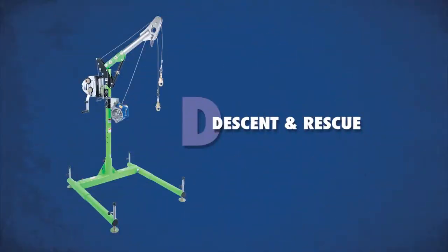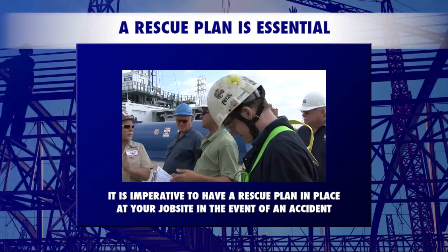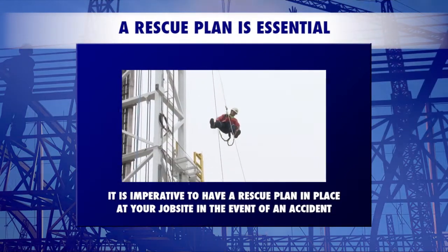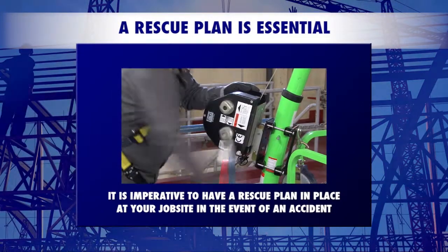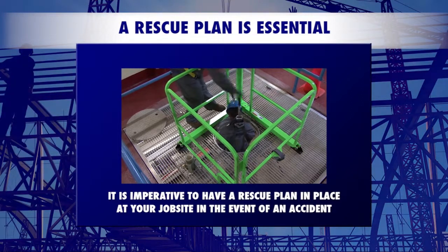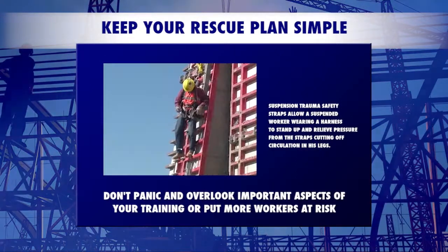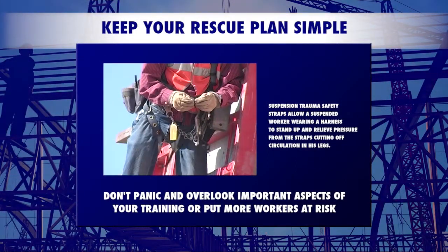Rescue and descent devices are used to lower an injured worker to the ground or retrieve him from a confined space. It is imperative to have a rescue plan in place at your job site in the event of an accident. And the plan must be reviewed and practiced on a regular basis. Calling 911 isn't enough. Your employees need to have the necessary tools, training, and skills to assist your staff or local rescue professionals. It's also important to remember that the rescue should be kept as simple and safe as possible, putting the fewest workers at risk.